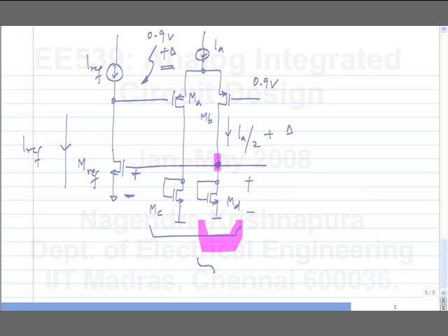So this you can do, right? You are designing the current sources yourself. So you can make sure that the quiescent current density here and here are the same. So there is no systematic offset between the quiescent voltage that you get and the quiescent voltage that you want. If there is mismatch, there is nothing you can do.